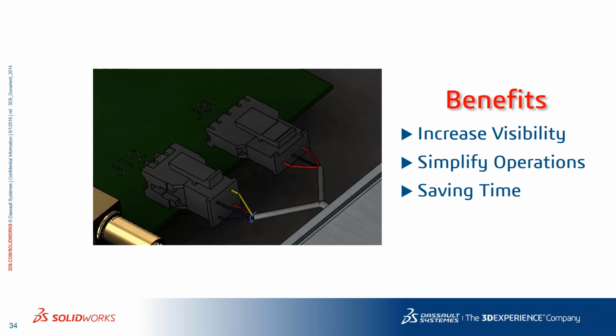One other thing that I always like to mention too is, as the electrical engineer, you have specific design intent, specifically segregation of your wires, which can be done. You can separate your power versus your comms. And in some cases, you might want to show that by using the 3D route features to show, hey, all my power needs to go here on this wall, and all my comms need to go over here to help avoid any type of interference.